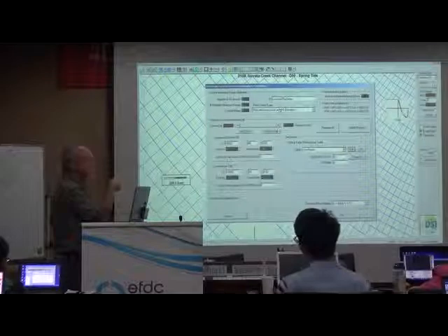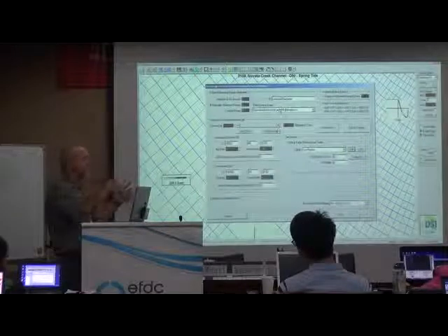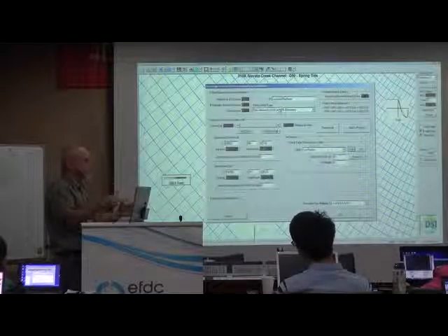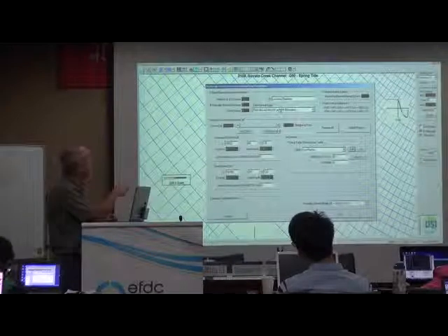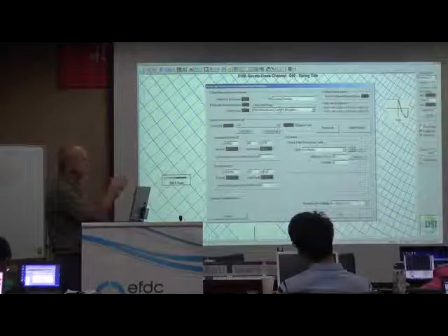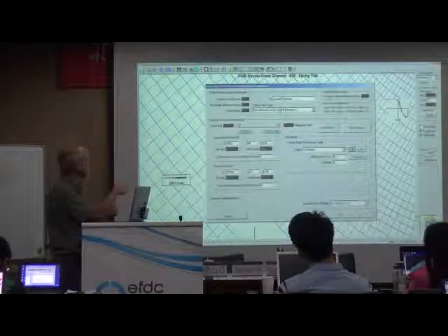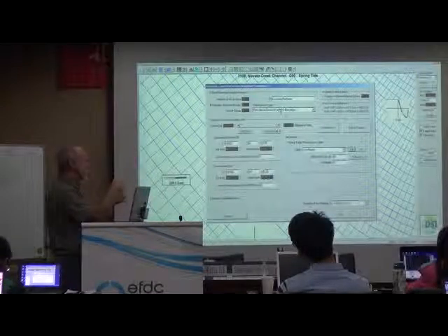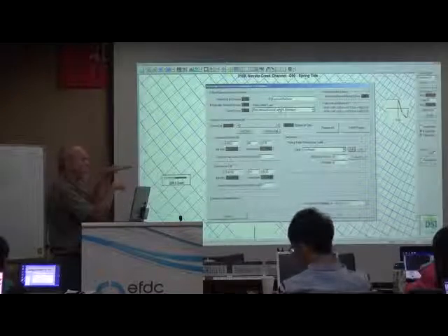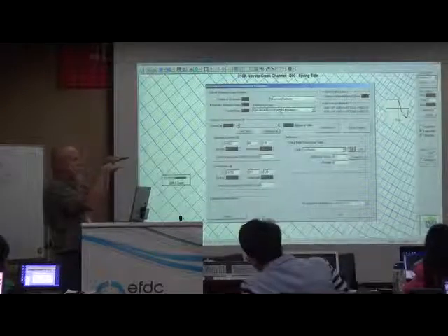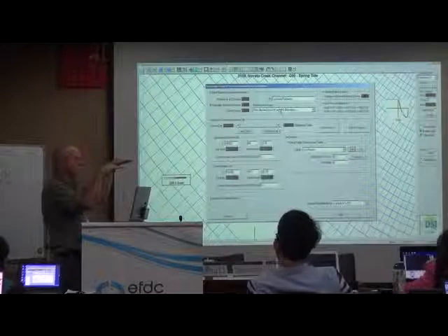Right. Whoever developed or is managing that structure designed that structure. You have a rating curve for that structure, and so what we're doing is we're just bringing that rating curve into the model, and what's coming into it are elevations. So I know my water surface elevation upstream, and I know my water surface elevation downstream.